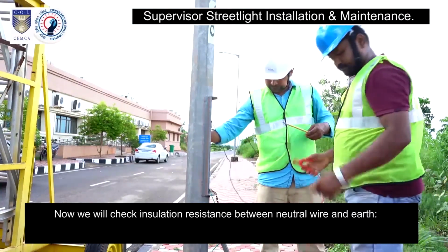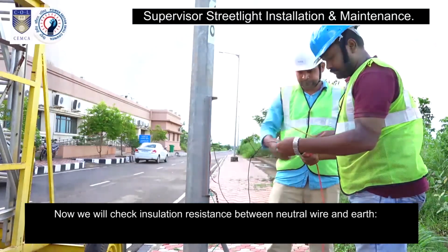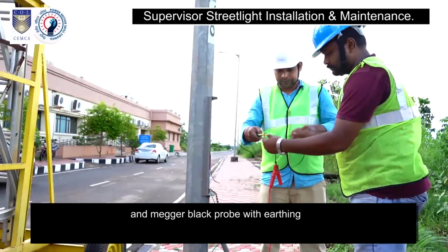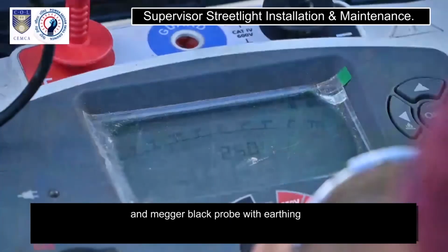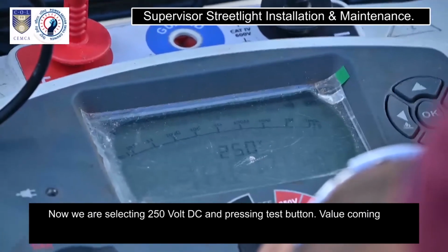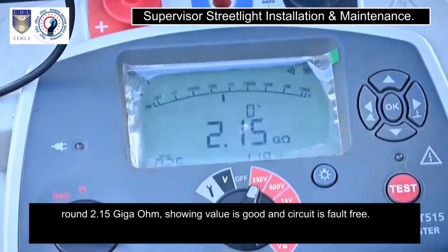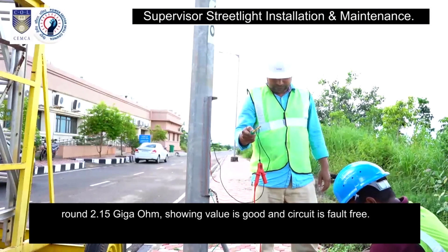Now we will check insulation resistance between neutral wire and earth. We have connected the red probe of the megger with the neutral wire and the black probe with earthing. Now we are selecting 250 volt DC and pressing the test button. Value coming around 2.15 giga ohm, showing value is good and circuit is fault free.